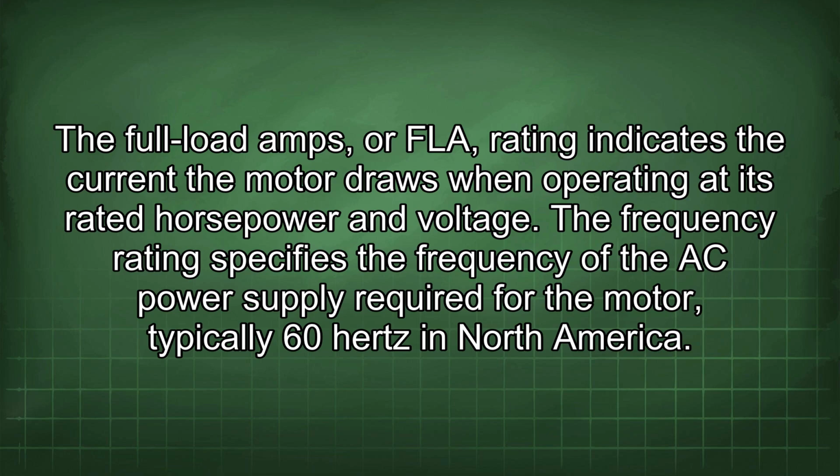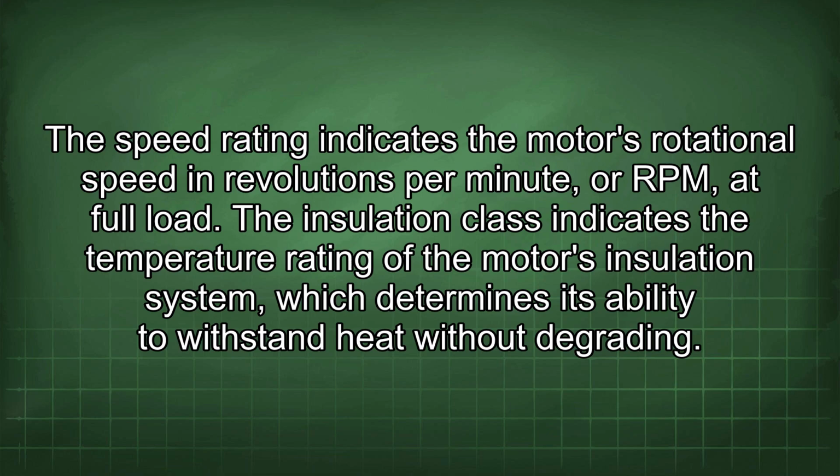The full load amps, or FLA, rating indicates the current the motor draws when operating at its rated horsepower and voltage. The frequency rating specifies the frequency of the AC power supply required for the motor, typically 60 Hz in North America. The speed rating indicates the motor's rotational speed in revolutions per minute, or RPM, at full load.